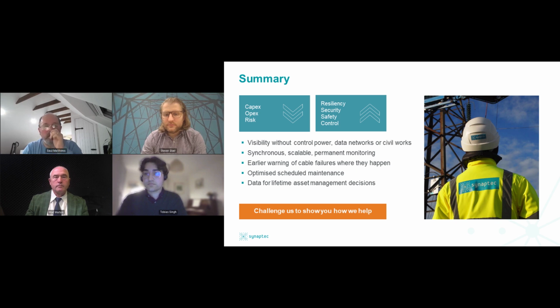Voltage is different, and you'd have to use a VT, but these are standard CTs and standard VTs that we use. The sensor is a passive device that's on the secondary side that's built into it, running off of the copper secondaries from these transformers. So it's actually very easy to retrofit, and we've done it several times.